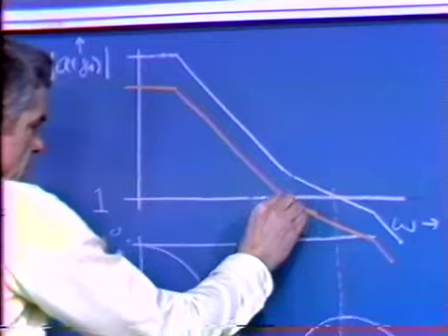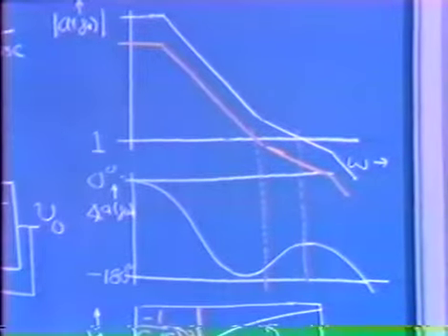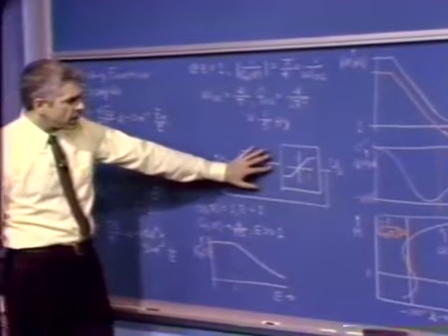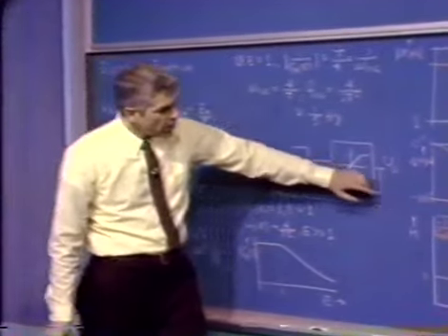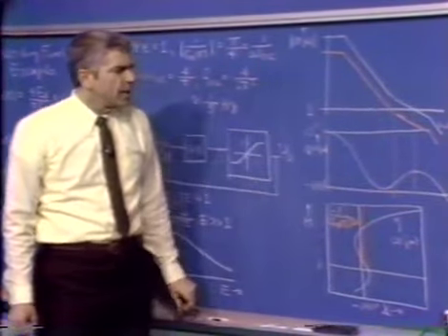And now we begin to cross over in a region that has very, very limited phase margin. And if we assume that we drove the system some way such that the signal at this point were even larger, we might be able to cross over at this very unfortunate point.